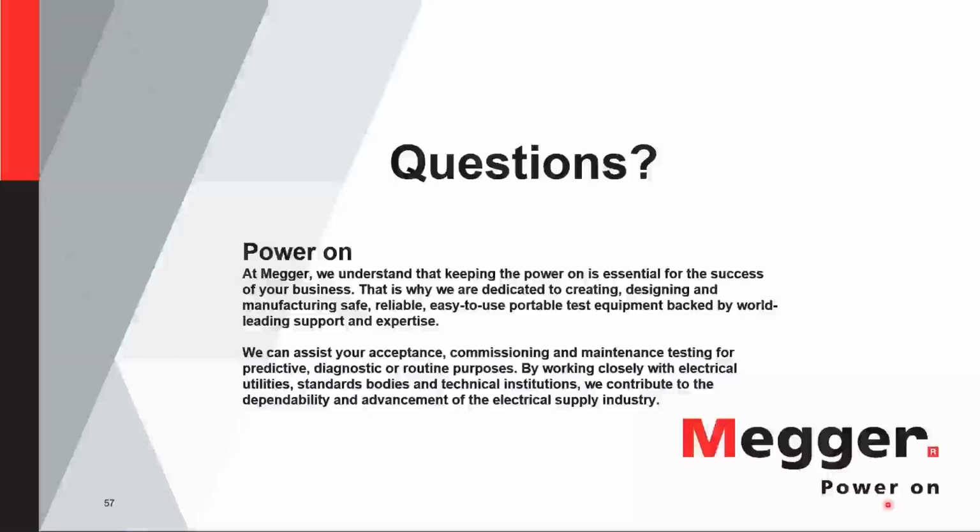Next question: is BDV criteria enough to decide on corrective action? And also, do we need to take into account moisture content, degrees of wetness, acid number, power factor, and IFT? Okay. Again, as we say in the electrical testing world, one single test cannot give you all the information that you're looking for.